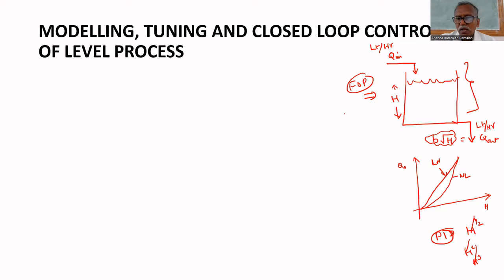If it is a first order model, if you see the root locus, how many poles will be there? Only one pole. In closed loop, if you increase k, the root locus will move to the left. That's why in the S-plane it never crosses the j omega axis. That's why a stable first order system is always stable in closed loop also.